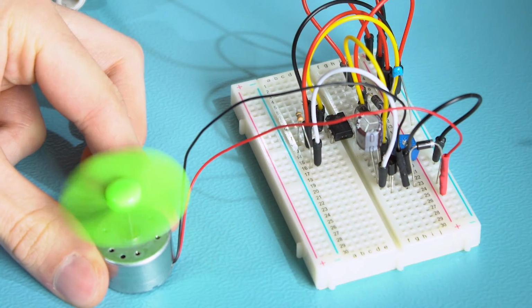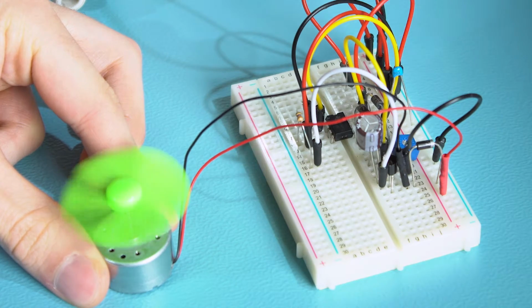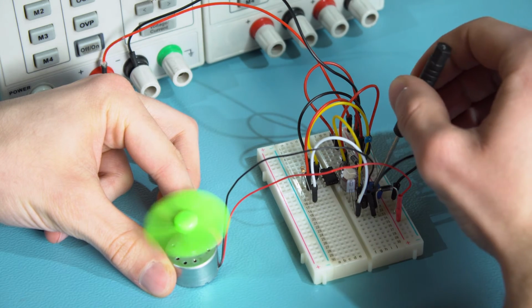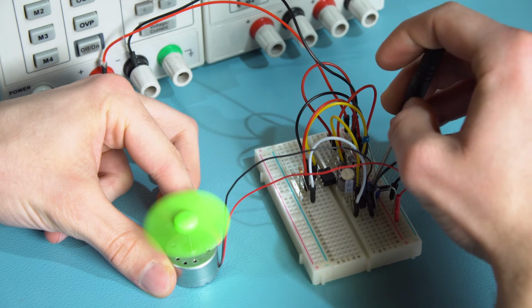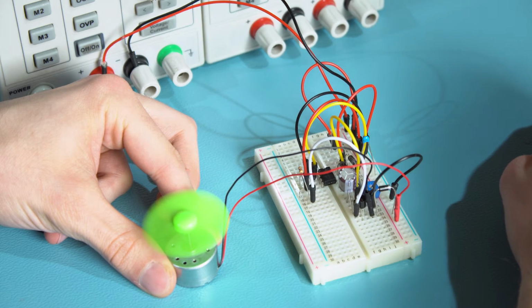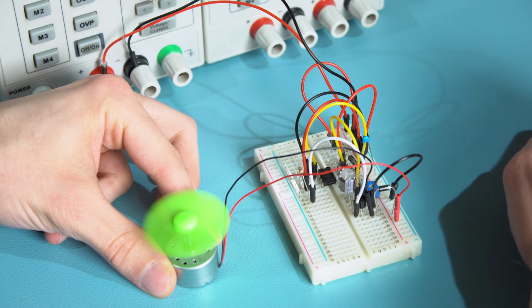In the extreme position, you can see that the engine does not stop and does not reach its full power in the other extreme. This is due to the fact that diodes D1 and D2, due to their voltage drop, limit the range of voltages which is present in some of the input circuits, so that the filling cannot vary from 0 to 100%.